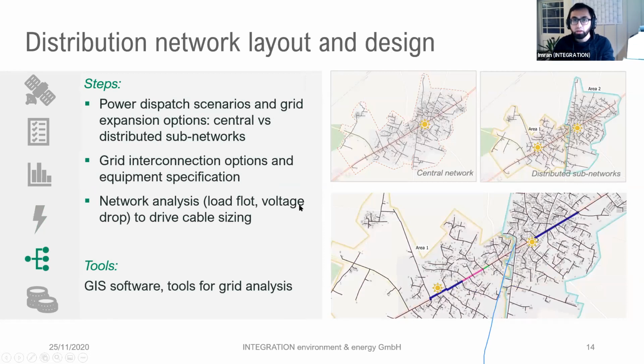At the same time, we look at the distribution network layout. And there we have several possibilities. You could have a centralized network, that is, you have one power plant providing for your big area. However, if you have systems at low voltage, for example, then you need to consider the boundary conditions as well. For example, a low voltage system is typically up to 1 kilometer or so. And if the system is becoming bigger, then sometimes it is even advantageous to break it down into 2 subsystems.